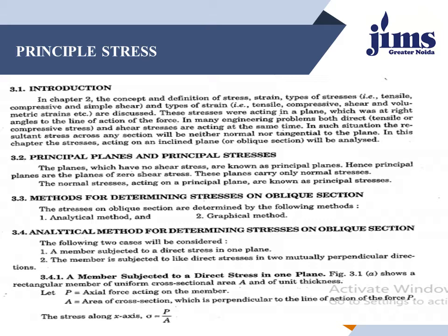So, first of all, what are principal planes and principal stresses? The planes which have no shear stress are known as principal planes. Hence, the principal planes are the planes of zero shear stress. These planes carry only normal stresses. The normal stresses acting on a principal plane are known as principal stresses.